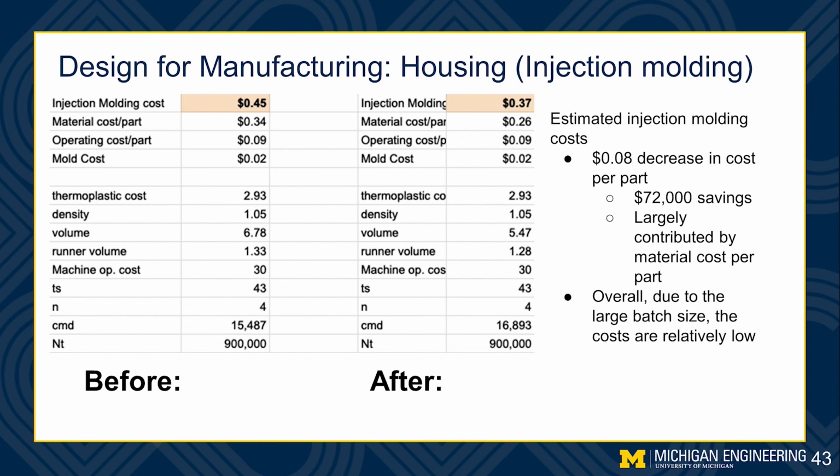This total number is relatively low due to the large batch size and cost effectiveness of injection molding, but some unseen cost savings such as easier part release, decreased cooling time, and more uniform higher quality parts are also a result of our redesign.